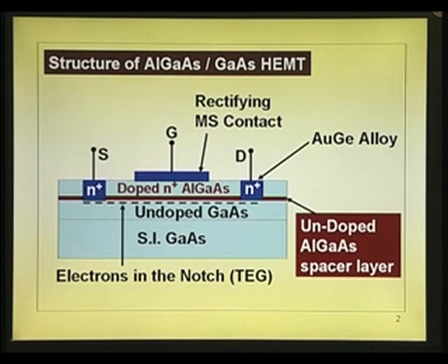Now, we have gone through the entire physics behind this, how it works, etc. And just like in the case of MOSFET, the structure is almost similar to MOSFET in one sense, in another sense it is similar to MESFET. If you just take only the top layer, N plus source contact, N plus drain contact, then doped aluminum gallium arsenide, that is equivalent of the MESFET. But we disable the MESFET here by putting a gate on this, which actually depletes the entire layer.